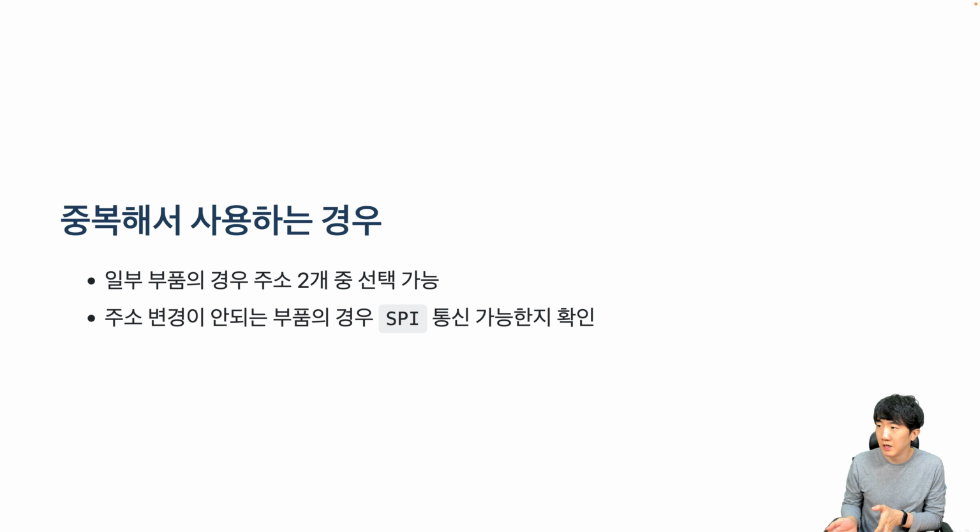If you want to connect the same type of sensor for use, you can refer to the datasheet to see how the address can change from 3A to 3B, depending on which pins are set to high or low. There are components that work this way. For those components, you can set the selector pin to change the address to avoid conflicts. However, there are also components that do not have this option, which leads to duplication.